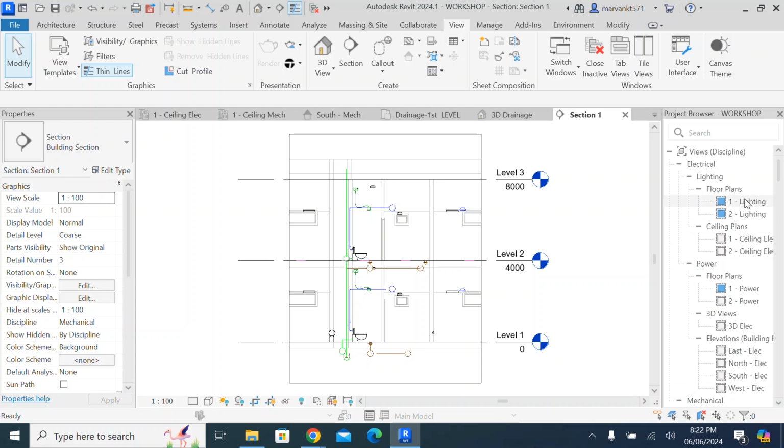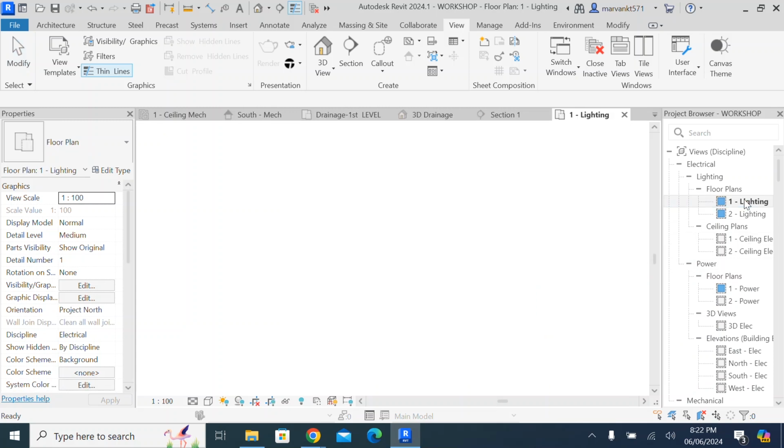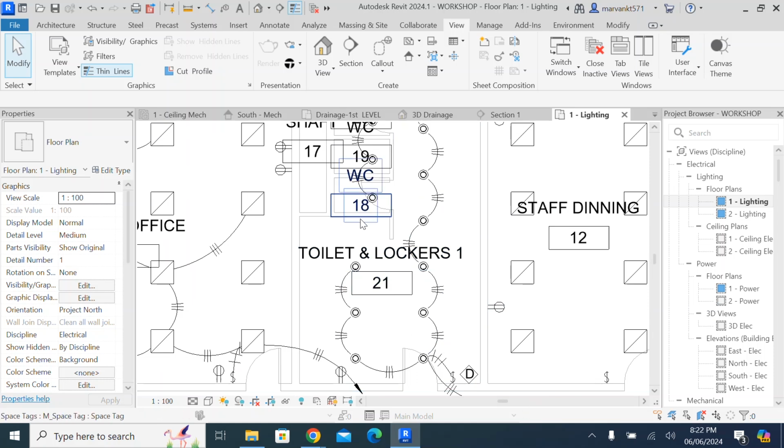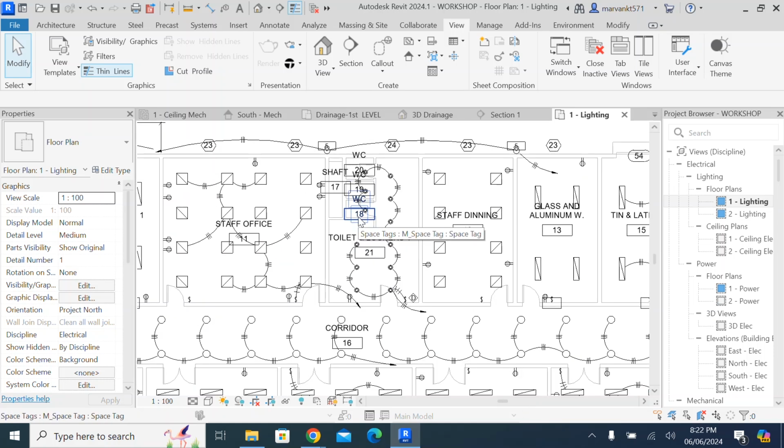And once you go to the lighting. In electrical, it has mainly two portions. One is lighting, the other one is power. So separately we have created the lighting and the power here. You can see the lighting with wires, and later so many other things you can do over there. You can create the panel schedule, then according to the panel schedule you can assign your circuit. Suppose your DB is a 3-phase DB, you can connect into R phase, Y phase, B phase.